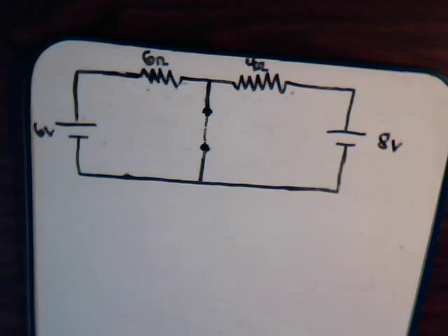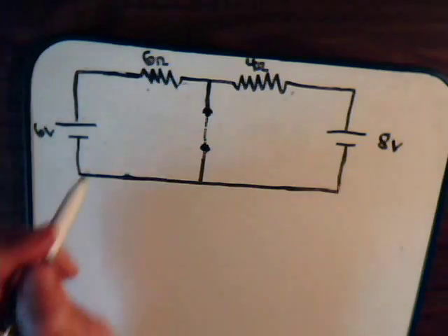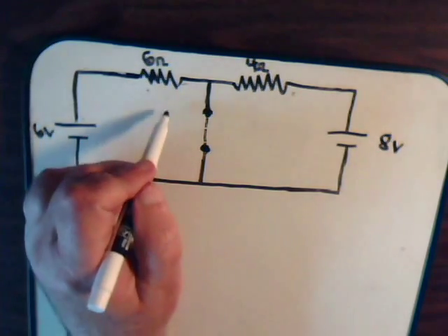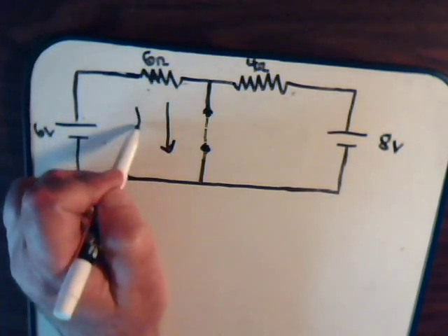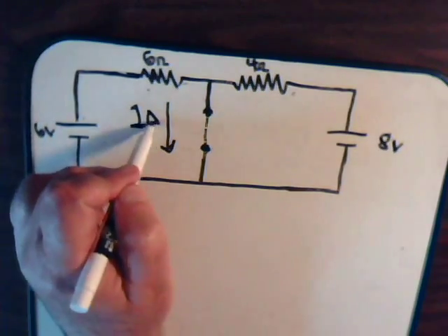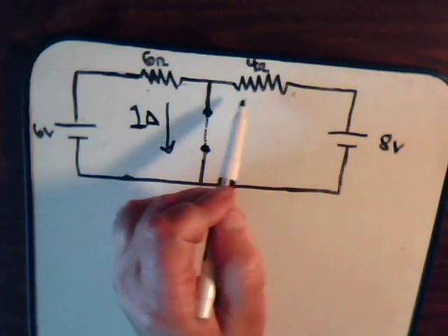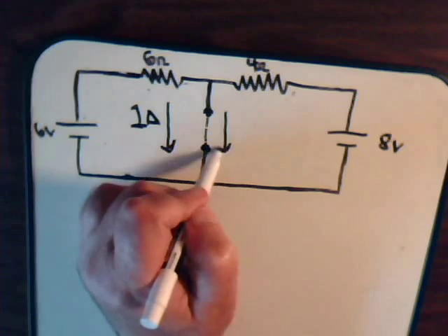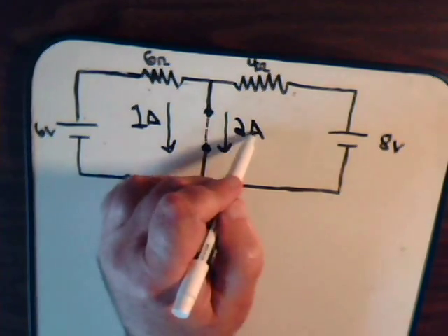The way we can determine that then is, imagine that this was just a conductor here, like this, and ask ourselves, what's the current going through it? So now we'll be a little bit smarter than what we were at the beginning of the video. We'd say, well, this puts 1 amp in this direction from that battery, and this puts out 2 amps from that battery.